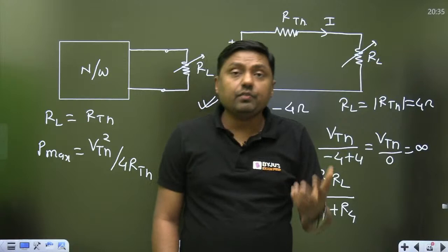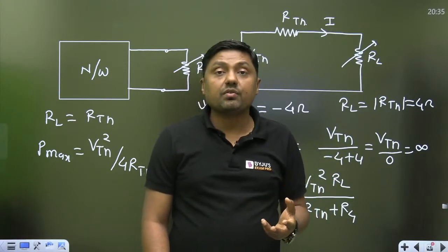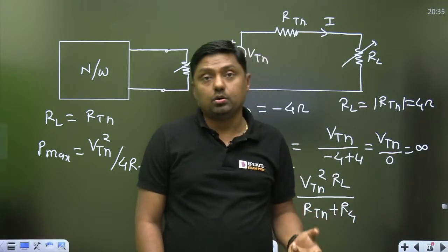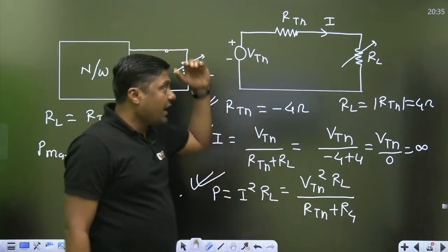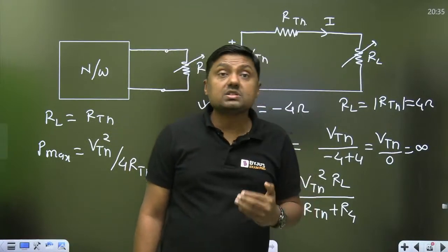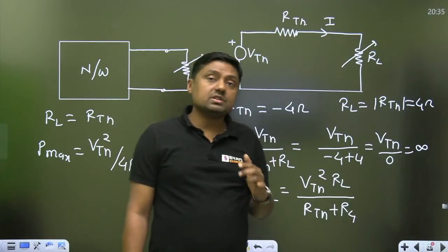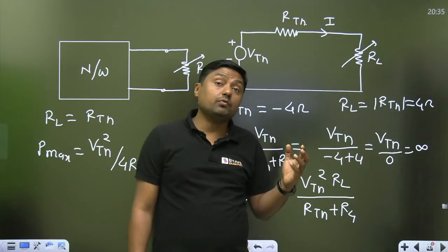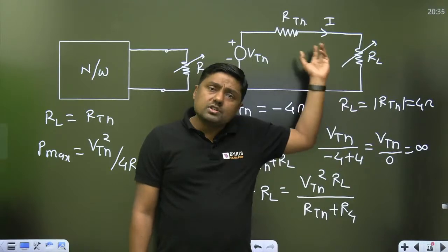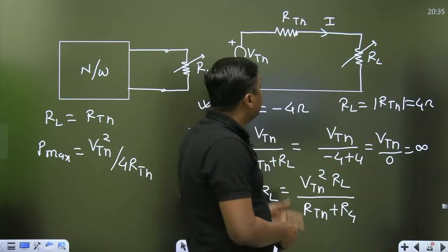We have negative resistance devices like what? Tunnel diode, Gunn diode. So that is active. Positive resistance will consume power, negative resistance will deliver the power. How is it possible that we are getting more power? Because of this negative resistance. Okay, right. Now the next one.